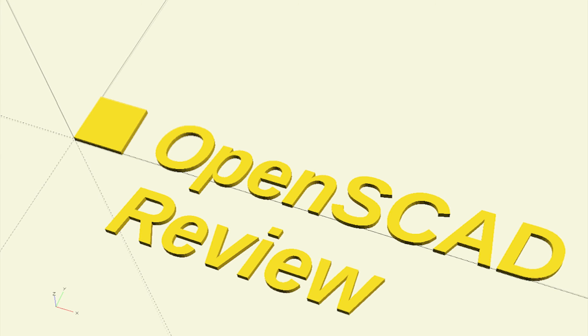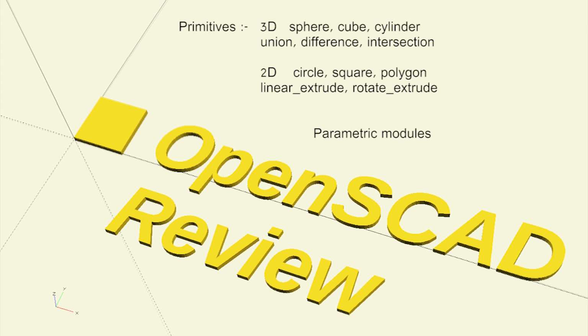This completes our introduction to OpenSCAD on the Raspberry Pi. If you have stopped the video and followed the examples, then you will have gained a good deal of experience in using OpenSCAD. You will certainly have made your Pi work. We began by looking at the 3D primitives, sphere, cube and cylinder, and how these can be combined in union, or reduced by difference and intersection. We then learned about transformations that change size, shape and colour.